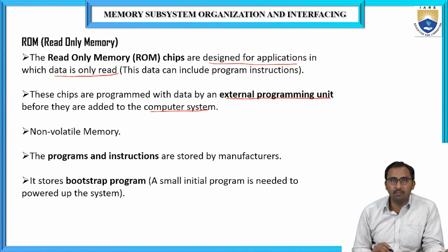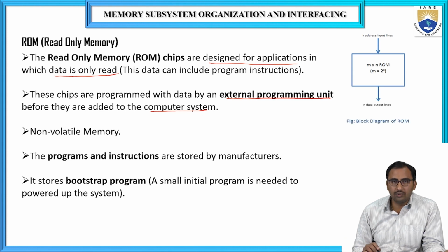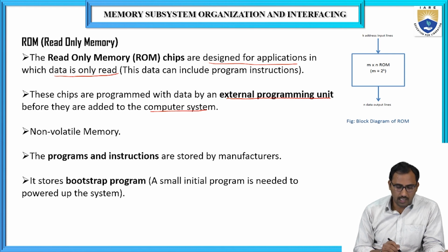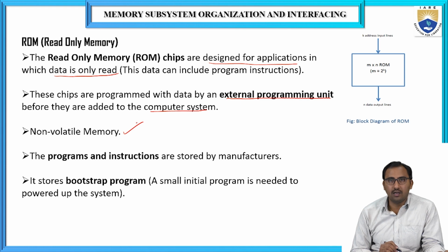So this ROM is available in the form of a chip. By inserting the chip into the ROM programmer, we can program it. By using the ROM programmer, we can load the program into the corresponding ROM chip. And it is a non-volatile memory. Non-volatile means even if the power supplied to the chip fails, the data stored in the memory will not be lost.